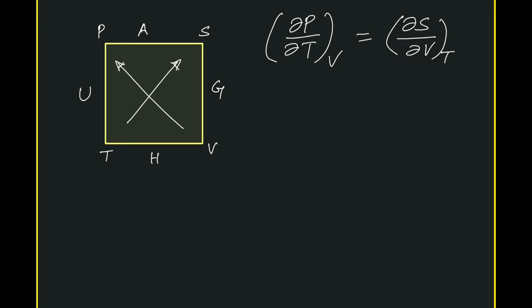Now we are going to obtain the Maxwell relation corresponding to dU. So what is dU? From the mnemonic diagram, dU equals, for U the side variables are T and P. For P the distant variable is V, for T the distant variable is S, and for P the arrow is pointing towards, so minus. T dS minus P dV is the relation for dU.